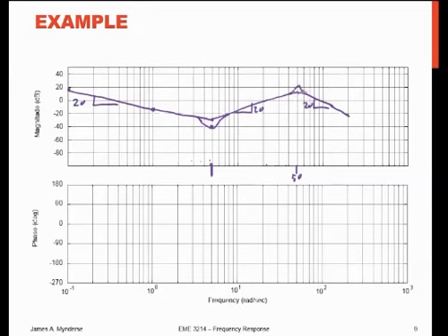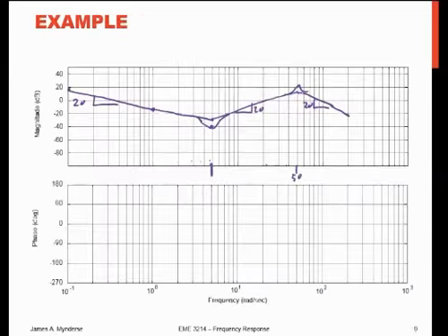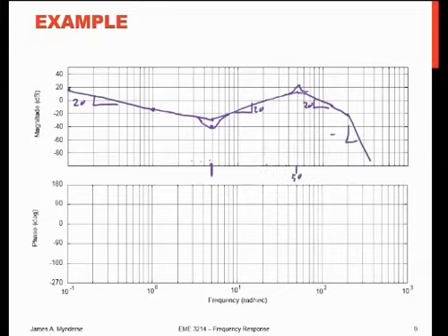And I have that peak. And at 200, try to steady my hand and hit that sensor. At 200, I roll off at 40 dB per decade because I'm adding another pole. Okay, and that's probably too steep the way I drew it there. Okay, so that is the magnitude, and I just kind of started at one end and added them up.